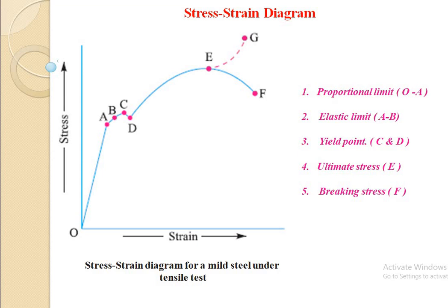The elongation is measured by determining the amount that two reference points on the specimen are moved apart by the action of the machine. Actually, this is the practical procedure. You have conducted this test and determined the strain in that component. That means we mark two points and measure the distance between them when we apply the load on the component.